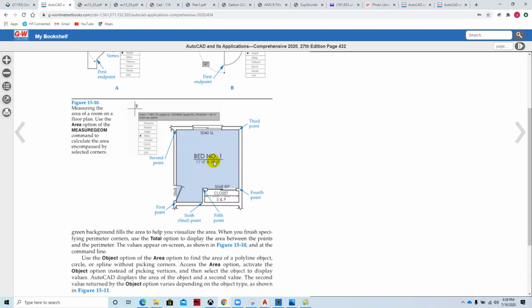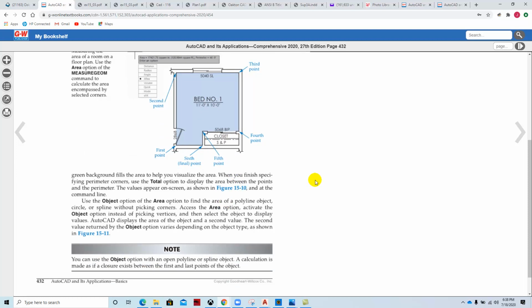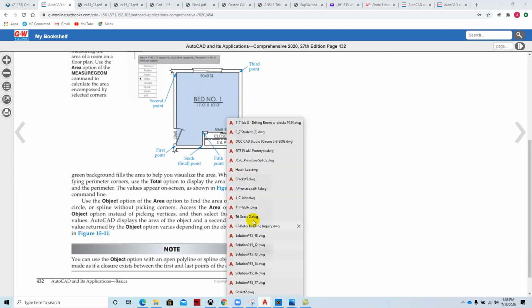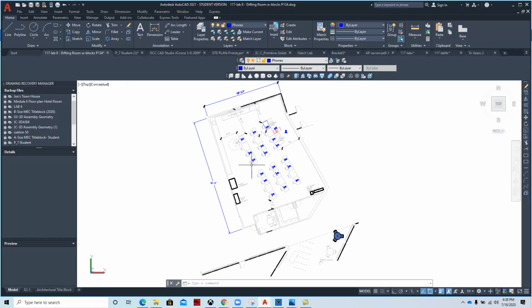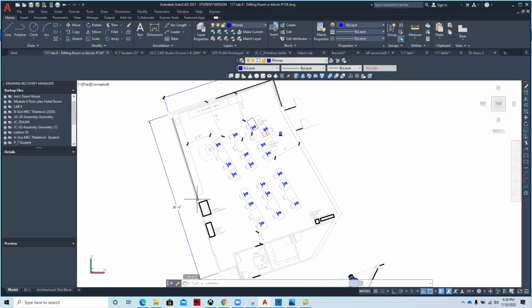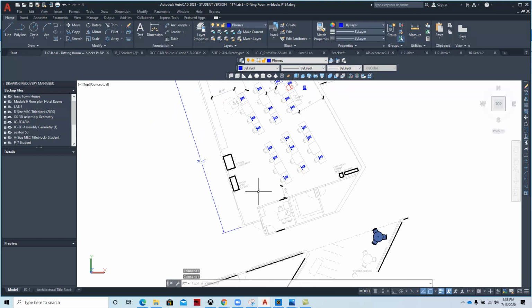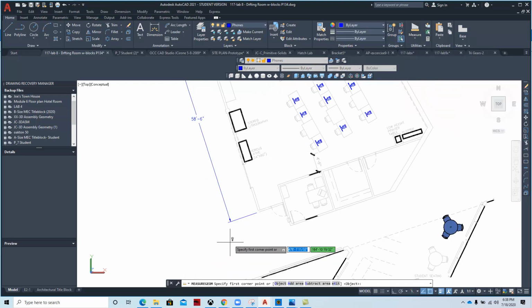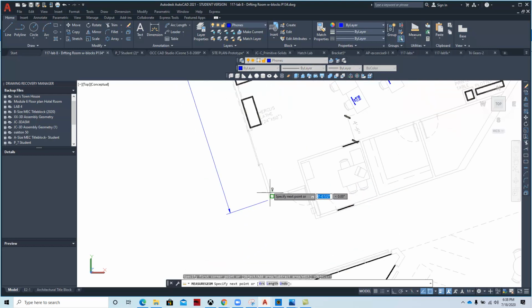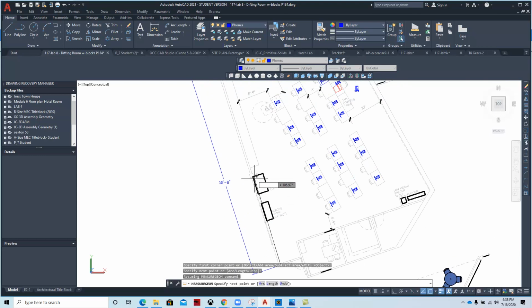Here's an example of a floor plan, and when we measure an architectural drawing, I'll show you how to do that with the Skokie campus. And so we have a Skokie campus drawing right here, and none of the walls are straight. So when we start to analyze it, what we're going to want to do is use the area command and an object snap. So we're going to say area, and then work through the area of the room,